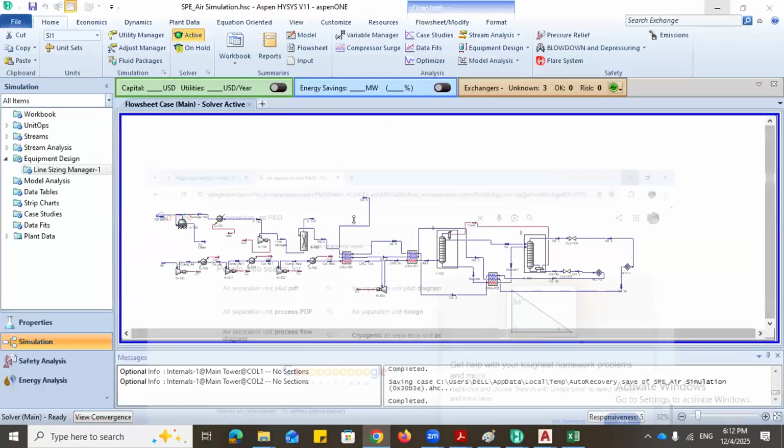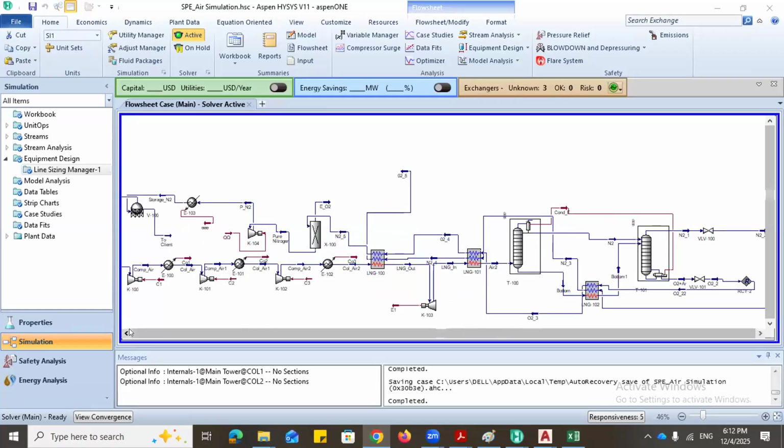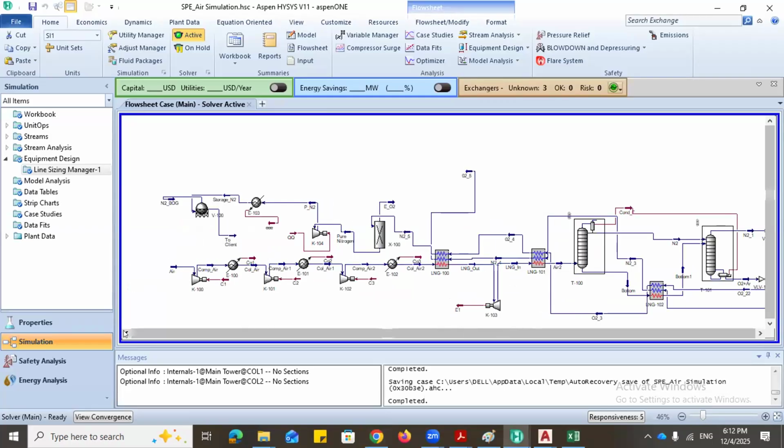So for the P&ID, what we call the piping and instrumentation diagram, we start developing it from the PFD. The PFD is one of the input deliverables required for developing the P&ID. As we are developing the P&ID, we have already started the 3D model, right? We are doing both of them simultaneously.